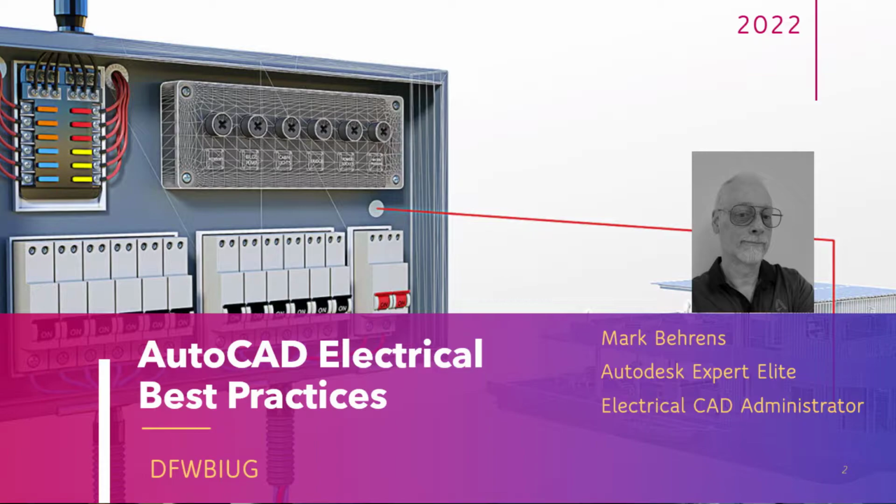However, AutoCAD Electrical is a very different animal from standard AutoCAD in the fact that when you look at the database, an electrical component has much more complexity than a standard block. It's got the electrical values tied to it. It's got connectivity. For example, a relay can have 4 sets of normally open contacts by part number in its database. If you go over it, you will get an error. A standard block will not have that level of detail.